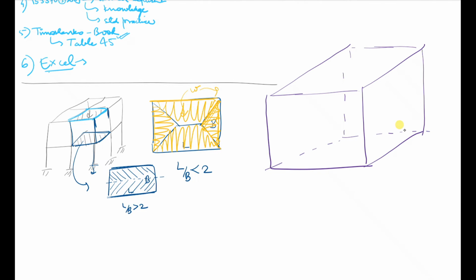So in this tank, this is the bed. We have these faces. Number one, two, three, four, and this five. And if there is a top slab, then six. Okay. All these faces are two-way slabs or one-way slabs, depending upon the case.